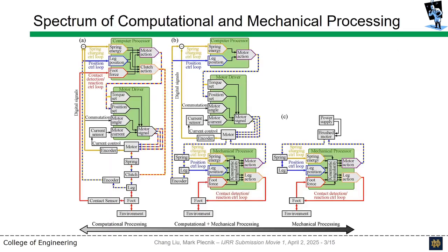That is, unless a clutch and a contact sensor are installed downstream. When the robot is out of contact with the ground, a clutch can engage to fix the distal end of the series elastic element, allowing it to be charged by the motor. Then when the contact sensor activates, the clutch can open to release this energy into a push-off motion. The immediacy of this reaction would be limited by the latency of digital communication, which can be a bottleneck for cost-effective electronics.